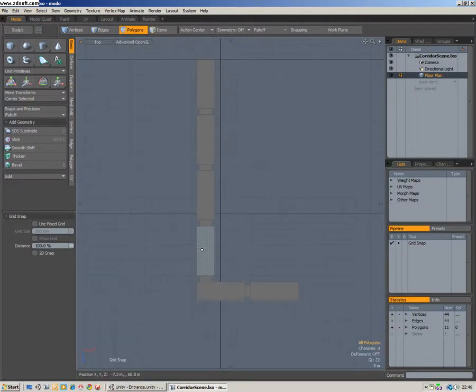But we'll be making some new assets, and I'll also go through importing assets, because when you bring in assets you may have bought, they might be in OBJ format or LightWave or something, and it's always handy to bring them into Modo first and then clean them up, because when you bring them in you might get a lot of materials made which you don't necessarily need, and funny normal maps and things, so it's best to load them into Modo first and sort them out before you start incorporating them into your level. So now we'll bang on with this.